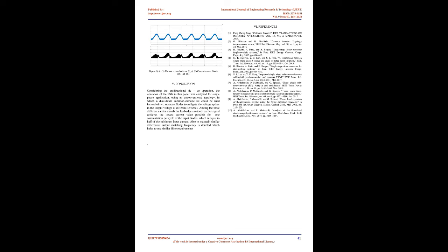Therefore, the sawtooth carrier switching frequency should be doubled to maintain a constant differential output voltage, and similar output filters should be used. Finally, due to commutation of diodes at the lowest possible value of current, there is a slight increase in the efficiency of the inverter when the lead edge sawtooth carrier is used.